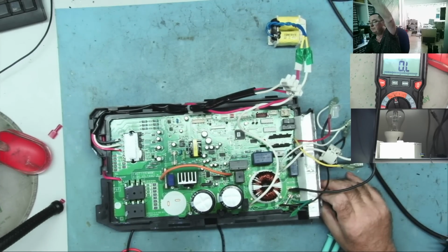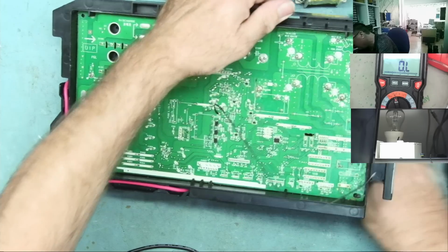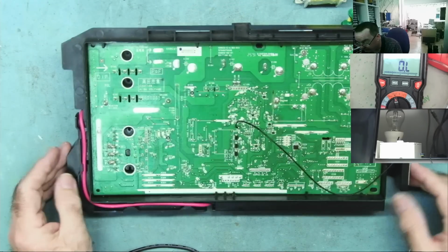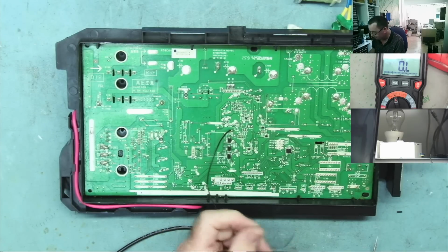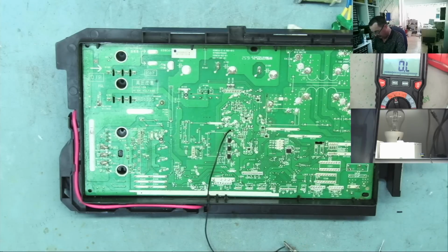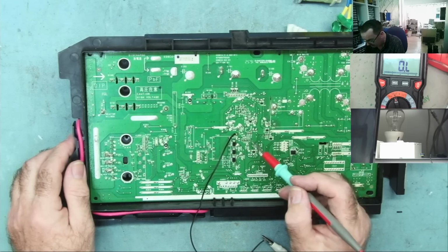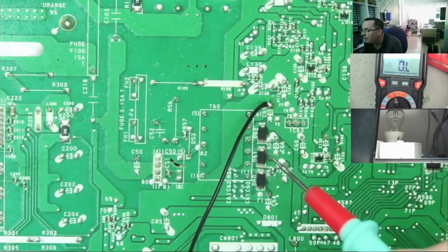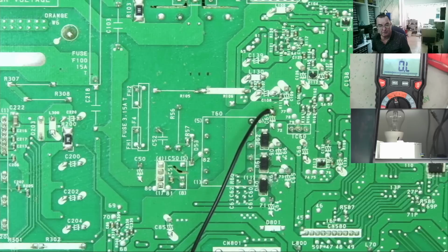I'm just going to flip the board over. Just make sure nothing shorts against anything. Get all the wires. Yeah, they all look fine. I have just tagged a wire on. This is ground, so I can put a crocodile clip on here, a little lead. I can attach my black multimeter probe, and then I have one hand free, which is handy. Okay, so we're going to be looking for the voltages around this 7805, and also on the outputs of these diodes, expecting to find a plus and minus something here.